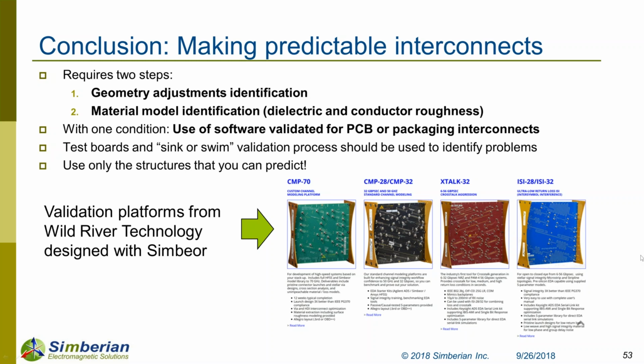And for signal launch sensitivity, when I was doing the optimization of the launch, I had as a goal to have return loss below minus 20 dB up to 30 gigahertz. But as you have seen, in reality, when we cross-sectioned the launch, everything's offset. So what should be done instead is make the launch so that you don't lose localization. Put the stitching vias closer, so that it's not so sensitive to manufacturing variations.